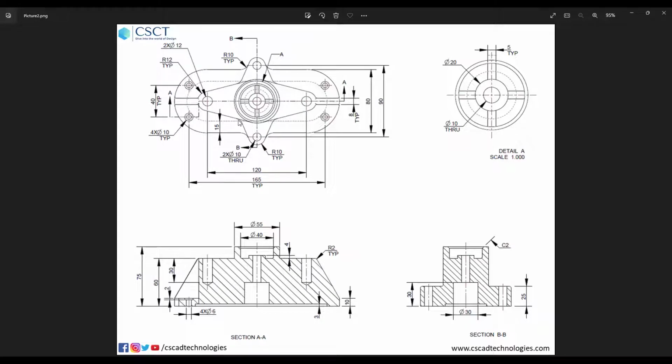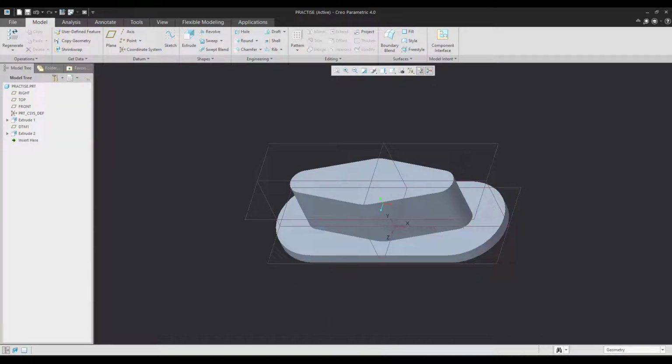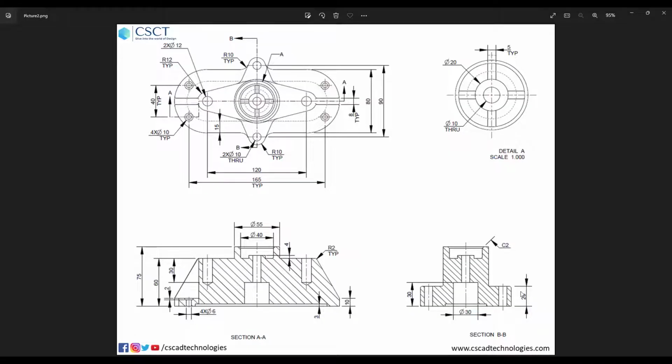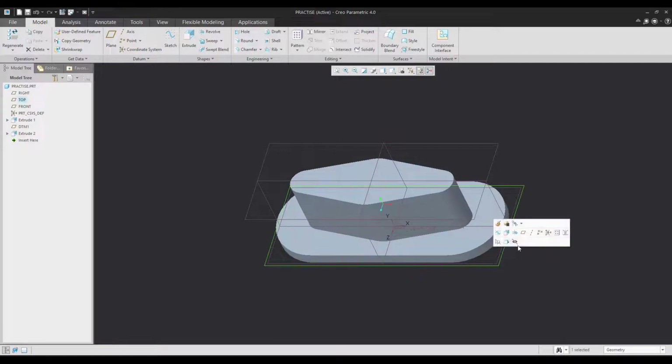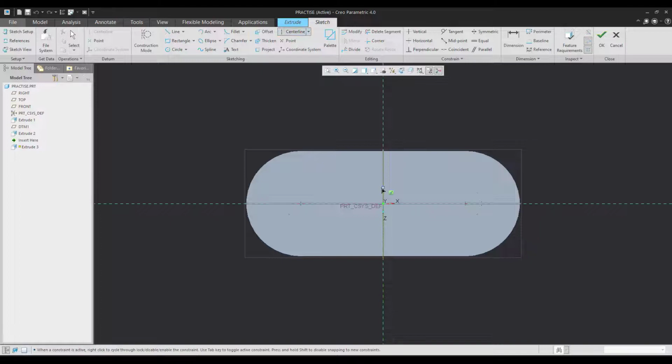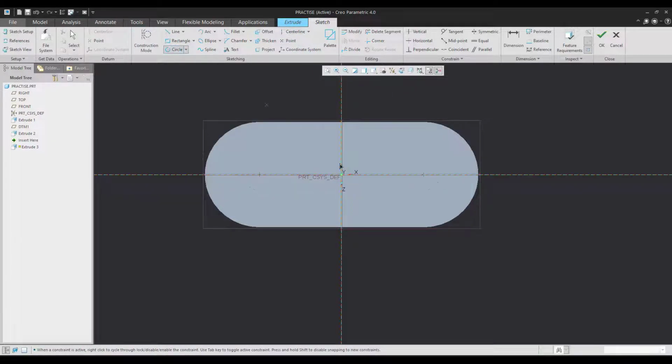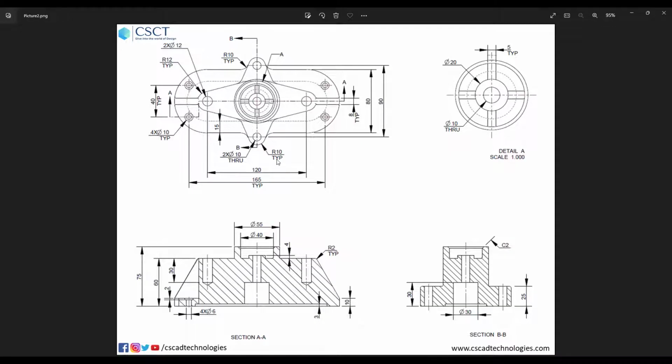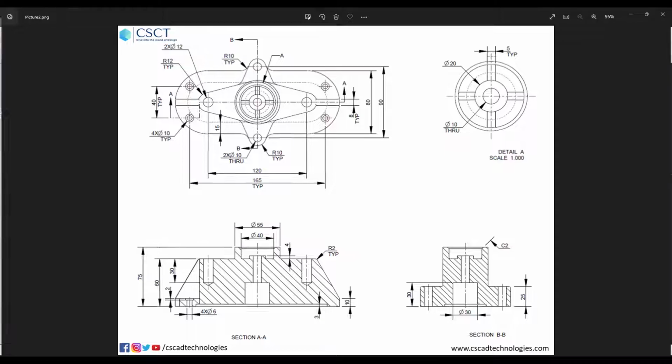We also have another addition which is of this shape, and the distance is at 90. So we can try to make this as well at the moment, but it's at a distance of 25. So you can take a plane or you can begin making that profile on the top plane itself. So I'd like to use the top plane, and I'll take the center lines so I don't have to struggle with the mirror like we did last time, and start making my profile. The profile is of R10 with a distance of 90.